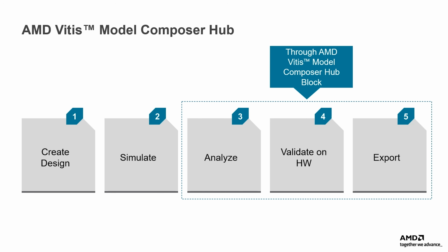The Vitis Model Composer Hub Block plays an important role in the Vitis Model Composer design flow. Once you create a design and simulate for functional verification in the Simulink environment, you need a Vitis Model Composer hub block to analyze the design, run hardware validation for the design, and export various outputs from the design.